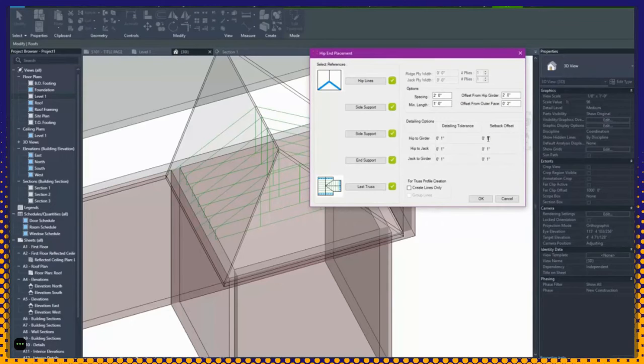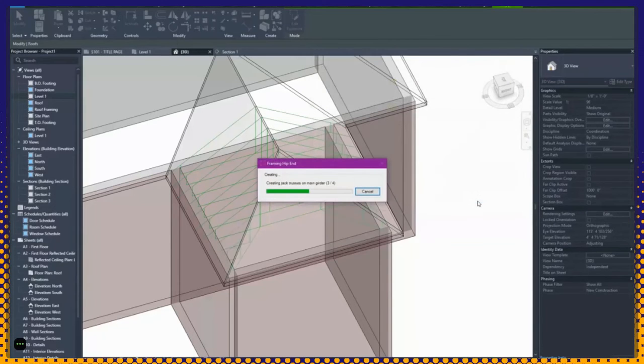And it's basically going to be half the size of the member that you're planning on using for the new trusses that are being created. So I'm going to leave these two at 1 inch each. You can definitely change them and play around with them based on the different sizes you may need to use. You can make it 3 inches, 4 inches, up to you. But I'm going to leave it at 1 inch and see how it places. Okay, we'll hit the OK button here.